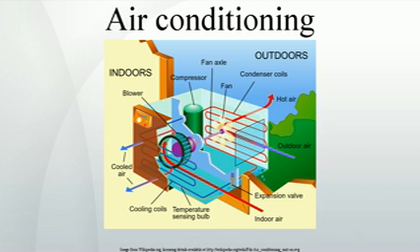Unlike other types of air conditioners, evaporative coolers rely on the outside air to be channeled through cooler pads that cool the air before it reaches the inside of a house through its air duct system. This cooled outside air must be allowed to push the warmer air within the house out through an exhaust opening such as an open door or window. These coolers cost less and are mechanically simple to understand and maintain.